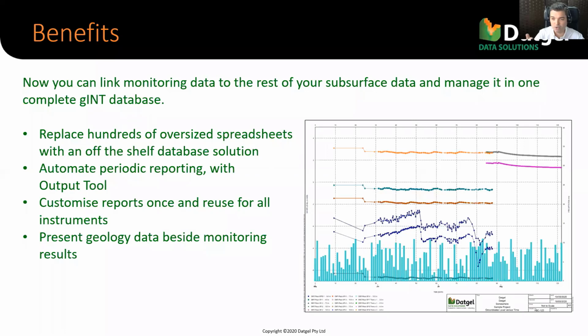Yes, we provide you with a whole suite of example reports, but you can edit them. You can reuse those edited reports or standard reports on future projects without having to edit 100 spreadsheets, right? It's the classic benefit of gINT in general, even for borehole logs: if you're using 100 spreadsheets and you want to change the presentation of your data, you have to go and edit 100 spreadsheets, and that takes an enormous amount of time. With gINT, the concept is you just have to edit the report once.